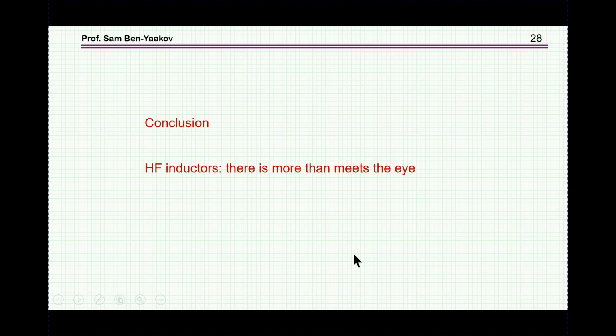So the conclusion is that high frequency inductors, well, there is more than meets the eye. They are not simple. There are many, many parameters, and if you like to do a decent design work, you do have to look at all these parameters and see how they affect your design. Now, not all of them are important, perhaps in a particular case, but they could be, especially if you work at high frequency and if the ripple is high, or if you're working with resonant converters.